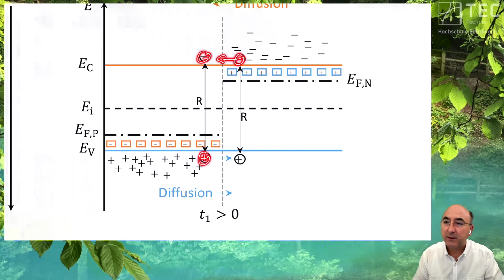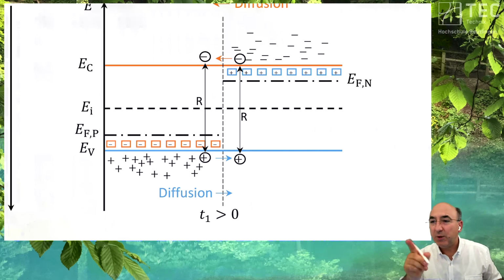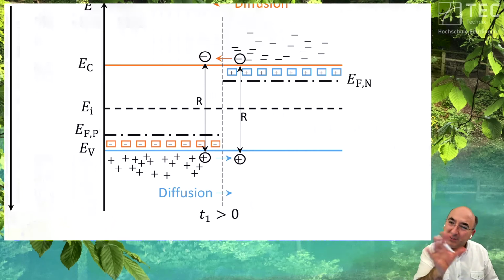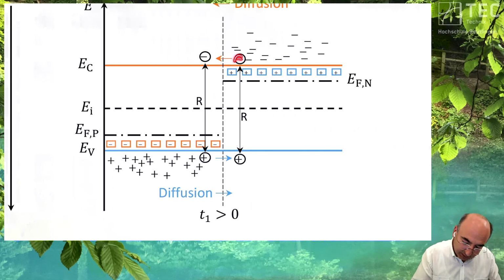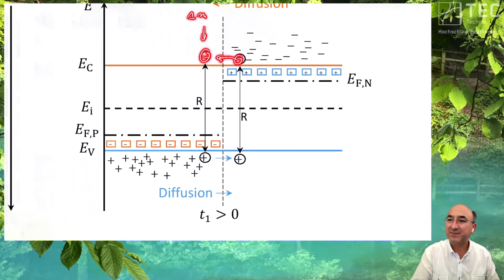can find. Now, Mr. Muka, you said, what happens now with the injection? Where does it come from? It starts here. It doesn't end here, but it starts here. So this electron is diffusing here. Now it's here injected. This is delta N. Okay, this delta N forces additional recombination.